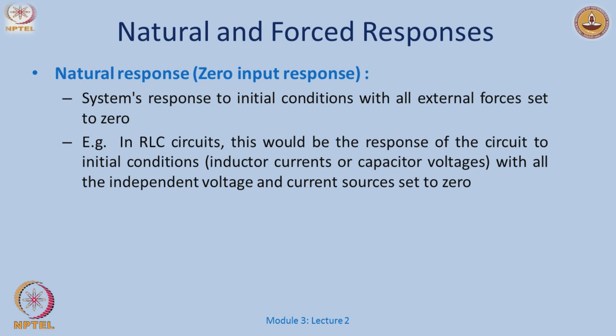It also is referred to as a zero input response, which means the system's response to certain initial conditions with all external forces set to 0. So, if I take a simple RLC circuit, this would be the response of the circuit with initial conditions. The inductor could have some initial current, or a capacitor could have certain voltage, with all independent voltage and current sources set to 0, which means there will be no external sources.